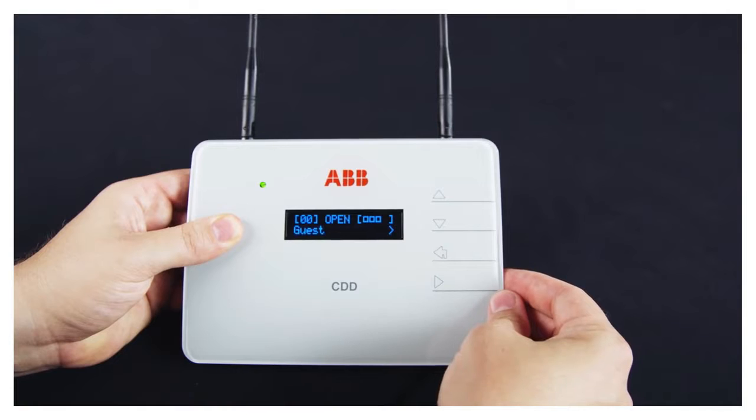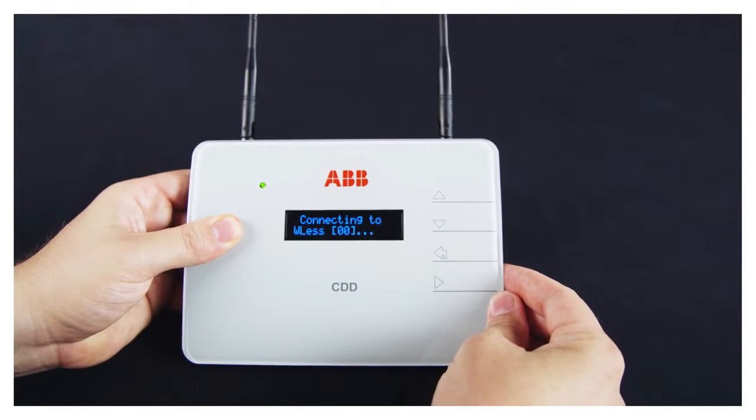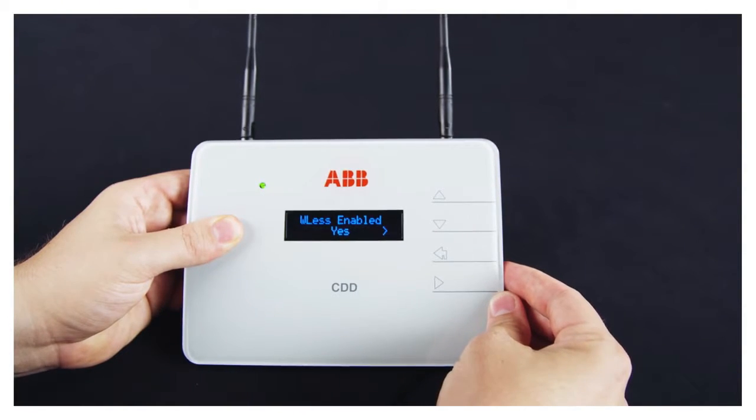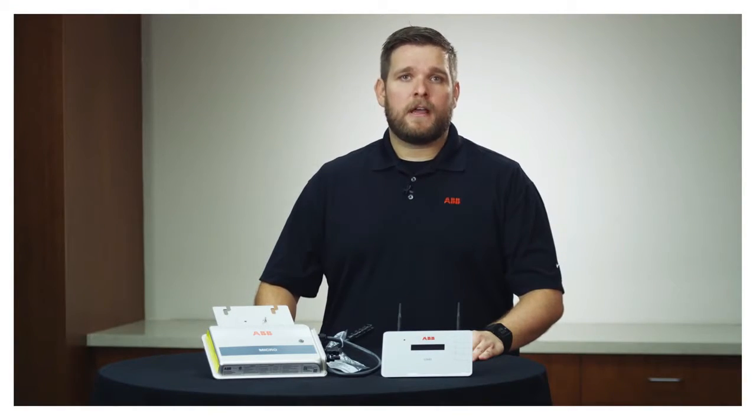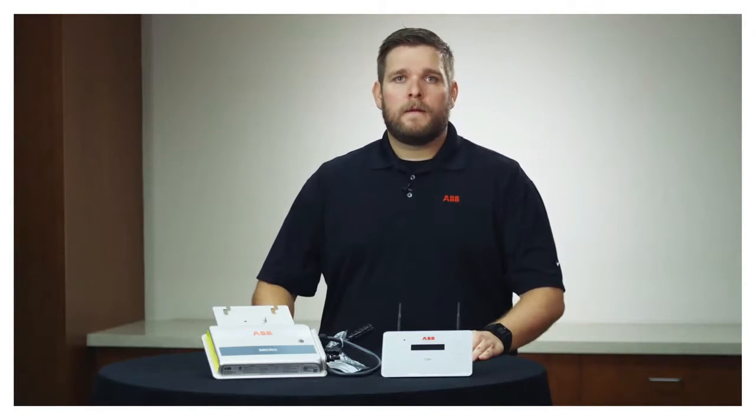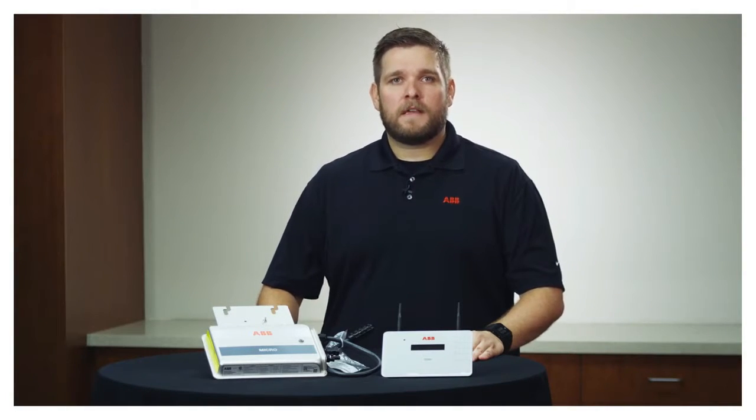If the homeowner has a secure network, ask the homeowner for their passkey. Press the up and down buttons on the CDD to scroll the list of characters, 0 through 9, A through Z, and special characters. Enter the passkey into the CDD. Press Enter to confirm each character selected, or press Escape to cancel the last character input. Press Enter again to accept the passkey.